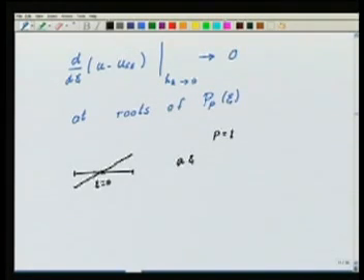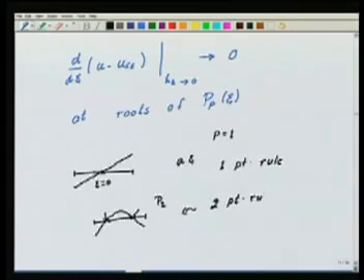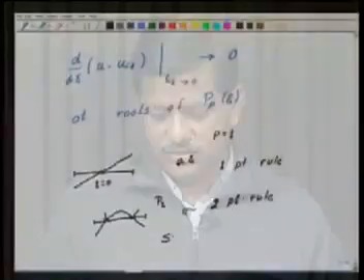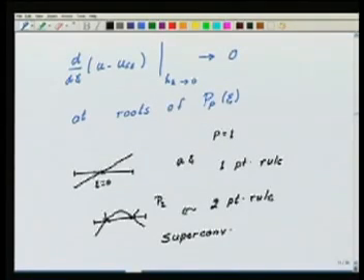Okay. Similarly, if I go to p equal to 2, I will see that the derivative vanishes at the two roots of p2. Now, what are these roots of p1 and p2? These are nothing but the Gauss points corresponding to the 1 point rule, the integration points. This is at the points corresponding to the 2 point rule. So, if I have obtained my solution using a p order approximation, I go to the p point rule and find those points. At those points, I know that the derivative of my finite element solution is going to be very good. These points are called superconvergence points.